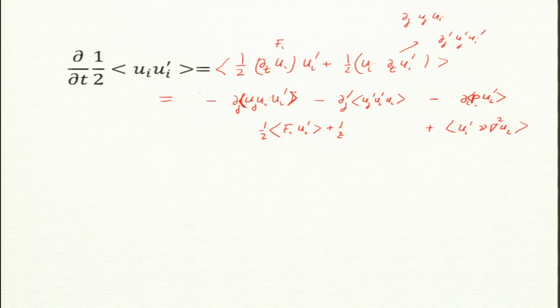What about this one, pressure with ui prime? This one is 0. For a given pressure, my velocity will fluctuate plus minus, it has sign. So, this goes to 0. So, the pressure term does not contribute, like our earlier derivation, for incompressible flows pressure drops out, gone. Now, by that logic, I can switch these derivatives, and these two in fact can be connected together. I will skip this algebra, okay. I will just write down the final step.